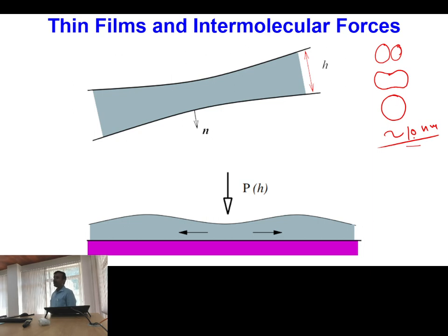So ultimately what will be happening in your numerical simulation, whenever two interfaces will be coming close to each other and gap between them will be of the order of 1 cell size, then immediately in the next step that gap will be gone and it will be coupled to each other. So two interfaces will be merging with each other. So that will be happening in your actual physical system. Sorry, that will be happening in your computational solver.